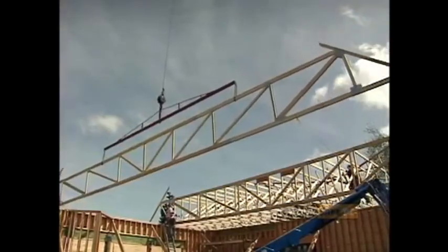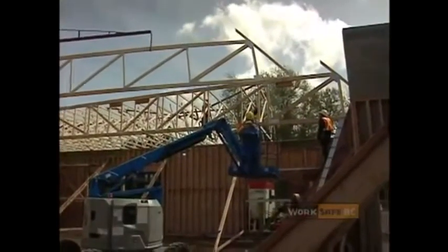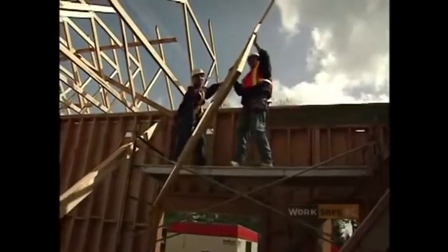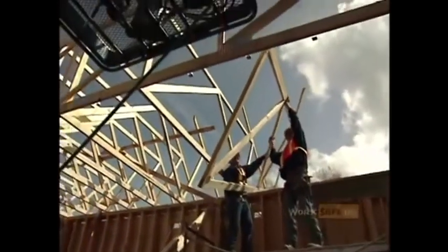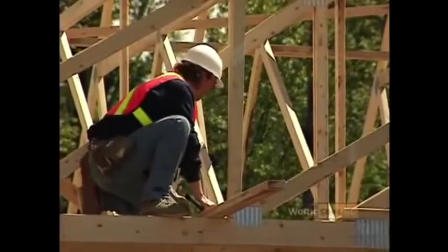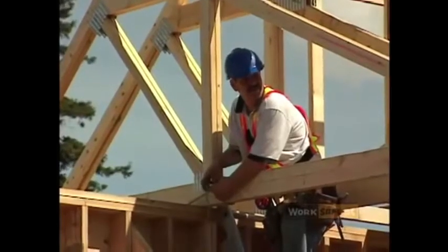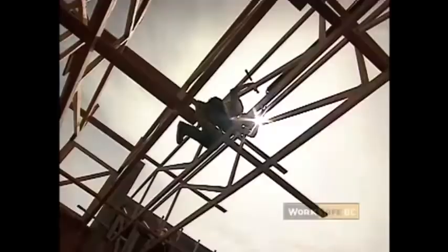Members of these trusses are joined together by means of pins, riveting or welding them to a common plate. Trusses are so constructed that all applied loads act at the end of the members. The weight of the truss members is negligible in comparison with the applied loads. In case the weight is not negligible, calculations are made on the assumption that the weight of each member is divided equally into two forces, which act vertically downward.